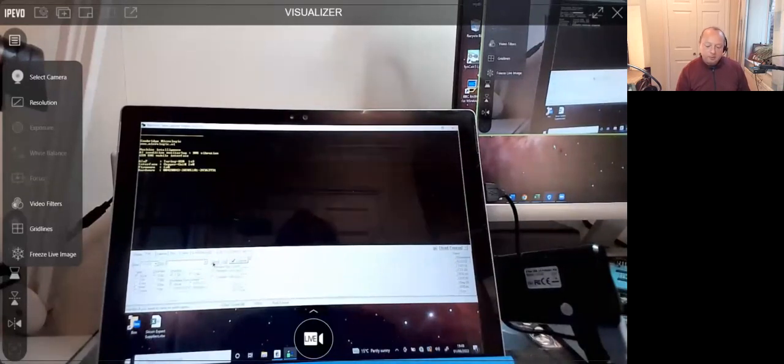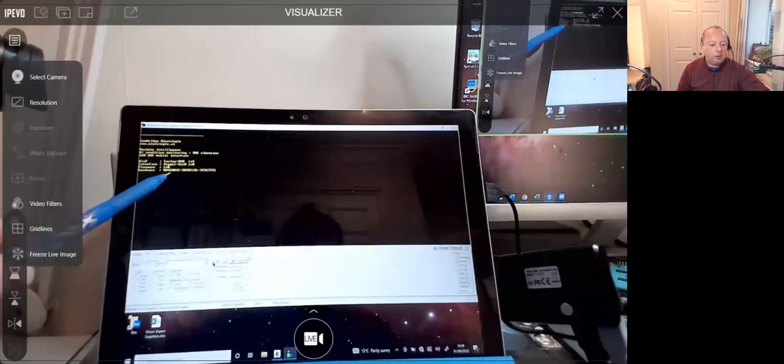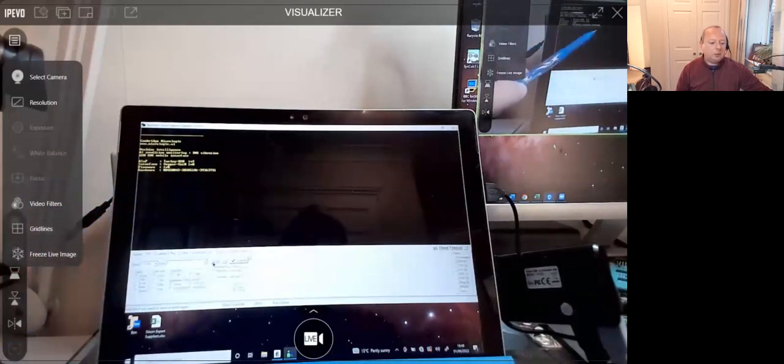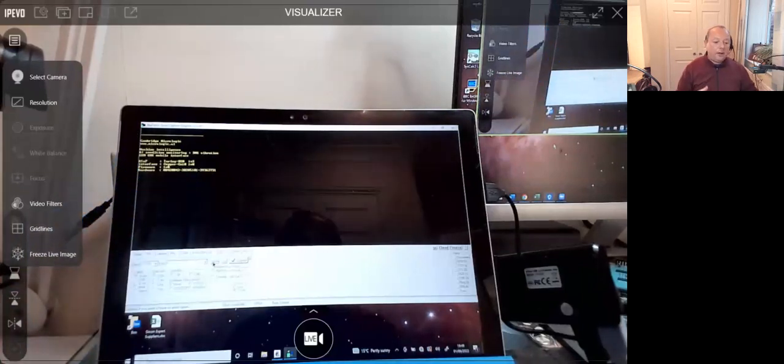I always put a little debug message in. So as soon as my microcontroller starts up, I've got a little routine that just squirts anything to the screen, your name, hello world, what it is you're tinkering with, and then you know for your debug that the UART is working. And just by way of example here, this is some work I've been doing. I just grabbed this one out the drawer. Obviously I have my name and I actually read out, it says hardware. This is actually the serial number of the actual silicon. So a lot of this is a text field that I create, and then I actually just read something from the chip. That way I know that my UART port is working perfectly.